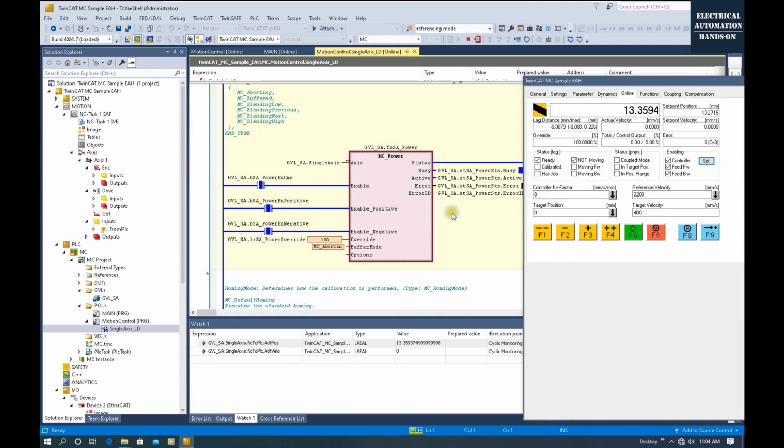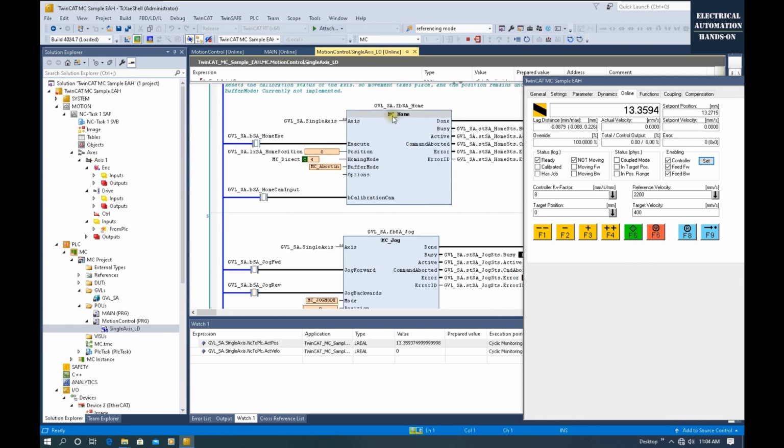Okay, the value now is at 13, so we can set a 0. Set 0, we can store down, and use this MC home. How to set the encoder to 0, or allow the axis to go back to home using the sequence, I will specially use one video afterwards to show this. Temporarily, I'm using MC direct.